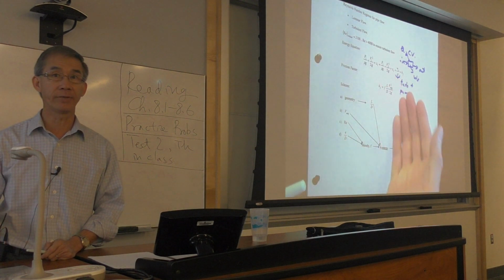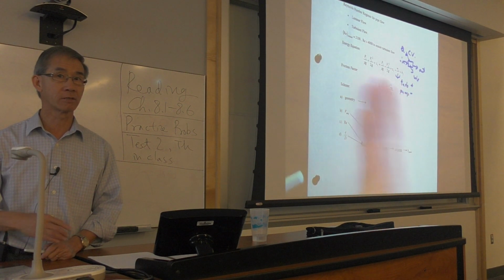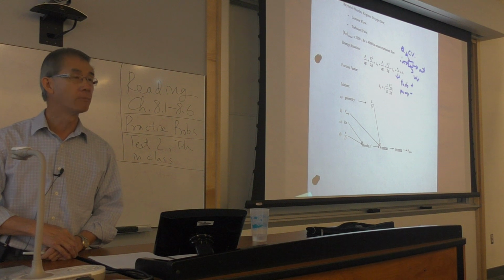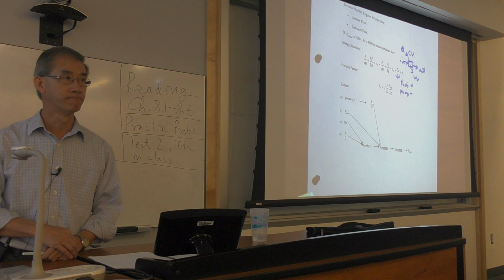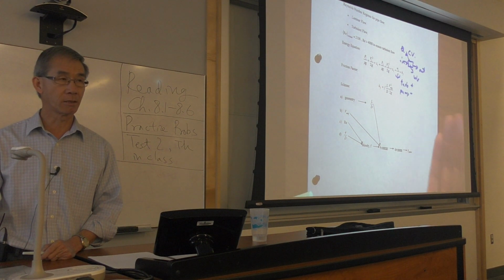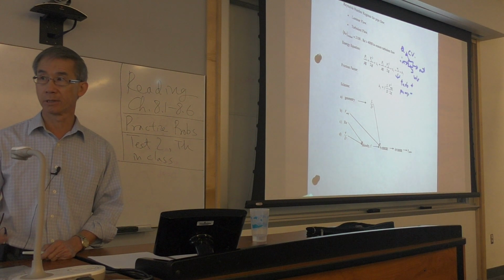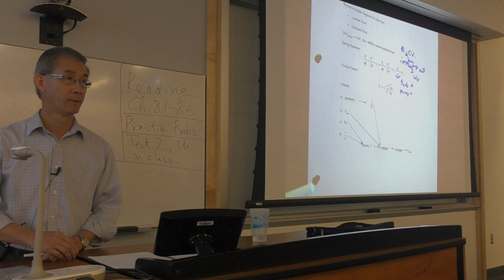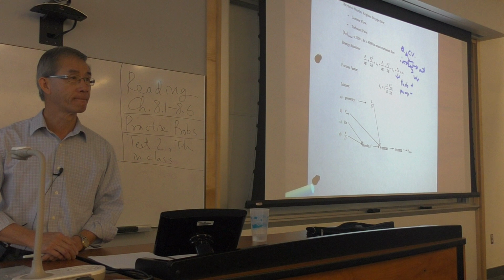And the added caveat is X sub F, the frictional head loss, must always be what? Positive. That's it. And the reason is the loss of availability. So the X sub F is always a loss. It's an increase in entropy. Yes? And for a compressor, shaft work would also be negative?